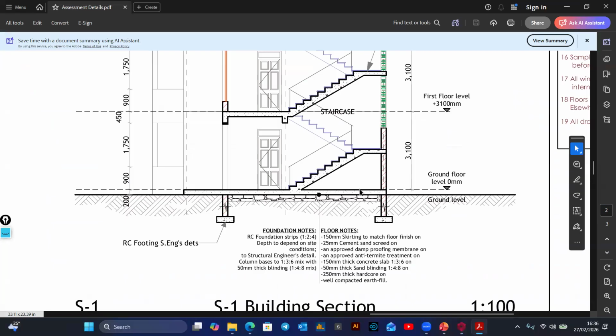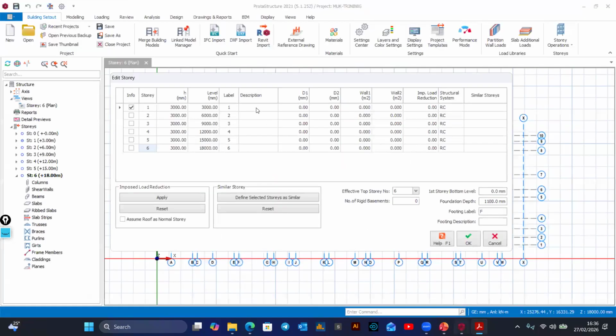This is called the plinth beam level. From the foundation, you add the plinth walls, and then on the plinth walls, you have the plinth beam. So in our configurations, this should be the plinth beam level.